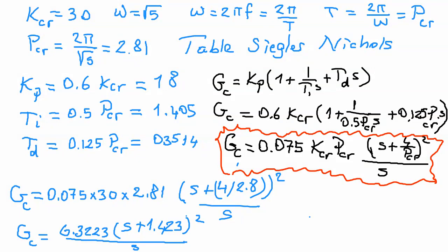We employed the second Ziegler-Nichols rule. We obtained the oscillation period, and we obtained the K value which caused the oscillation, the limit on the J omega axis. And then we employ the second Ziegler-Nichols chart. Look at the chart. It's already here.